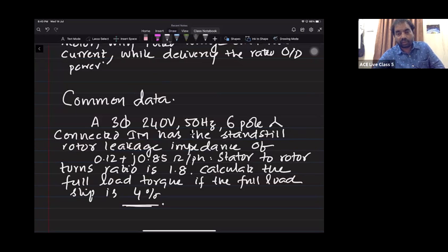There is no need to get the speed and torque relation. Simple. Whenever you increase the load, as I wrote yesterday, speed decreases, relative speed increases, flux cuttings increase, EMF increases, current increases, power increases, and the torque will increase. Please remember.